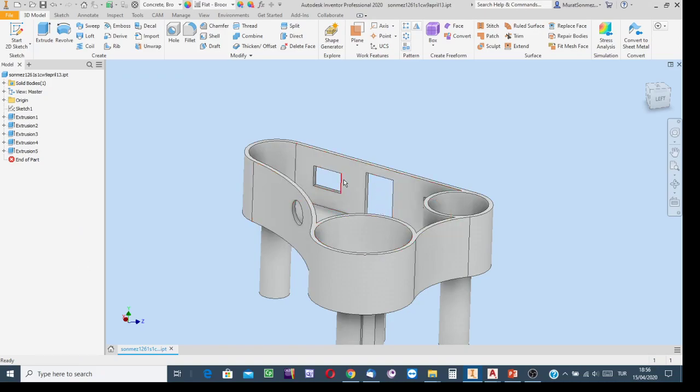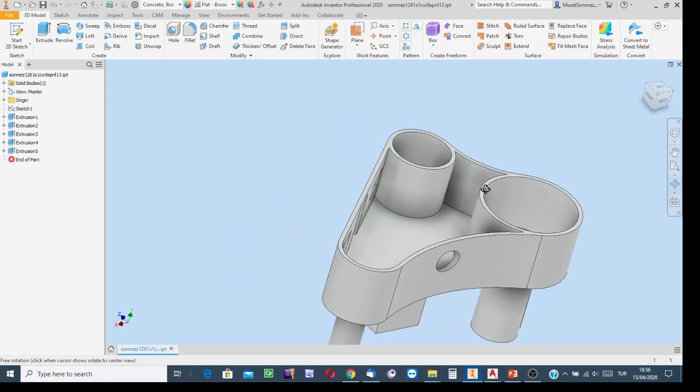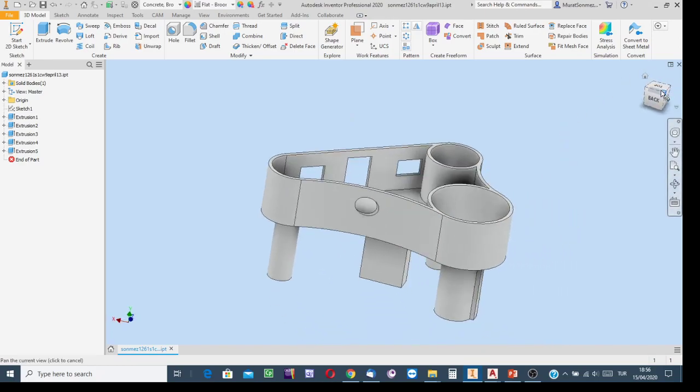You see, although I drafted the sketch over the flat surface, using the To facility of the extrusion process I managed to create the empty space over the curved surface, within the curved feature. And you see the edge of this space is over the curved surface. Okay?